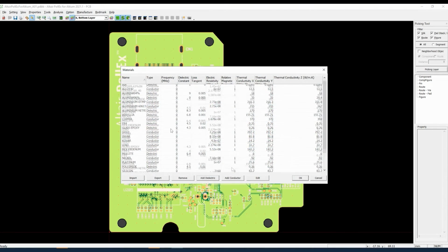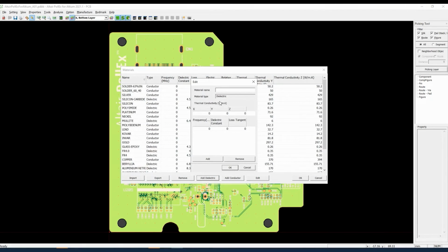Similar to the signal integrity, we have to add material data. And in some cases, we can actually reuse the same information put in during our signal integrity analysis. I'm adding in a thermal paste in case I were to use that to increase our efficiency of understanding how we can decrease the operating temperature of some of our main components.